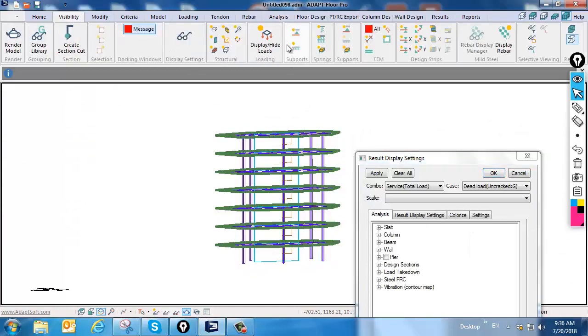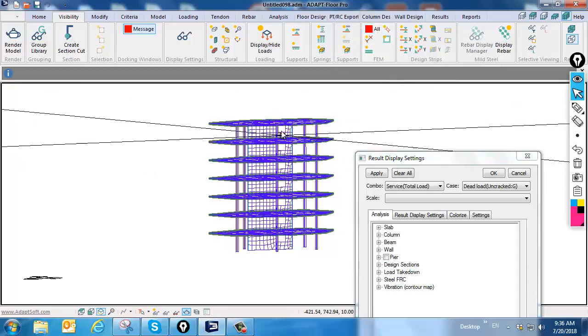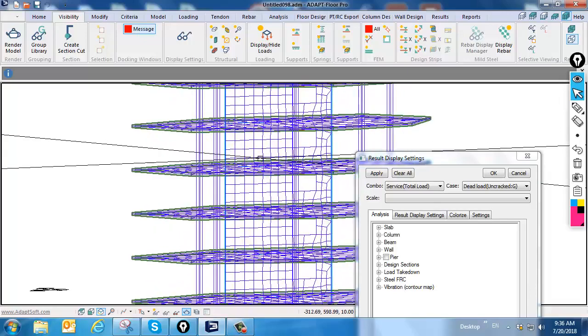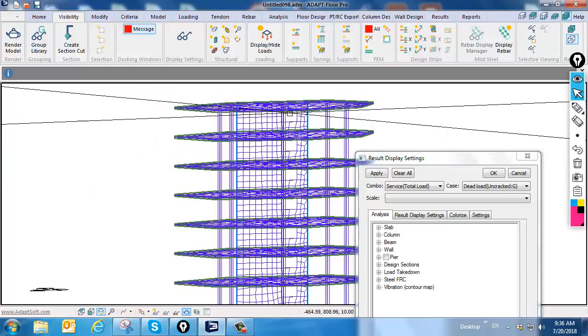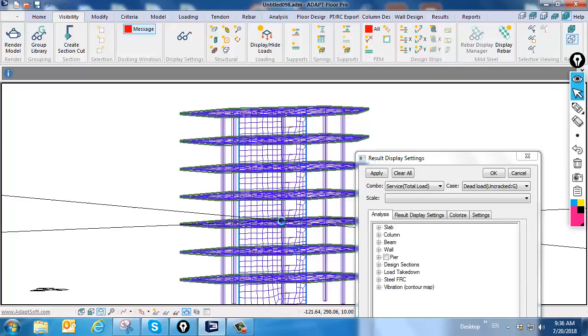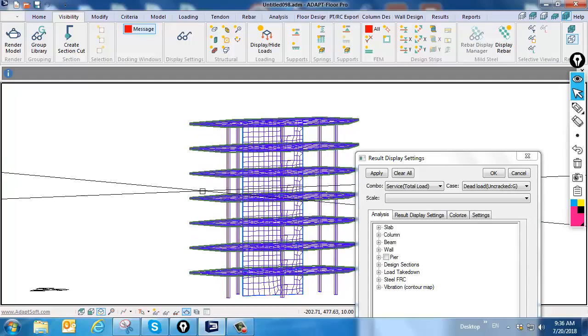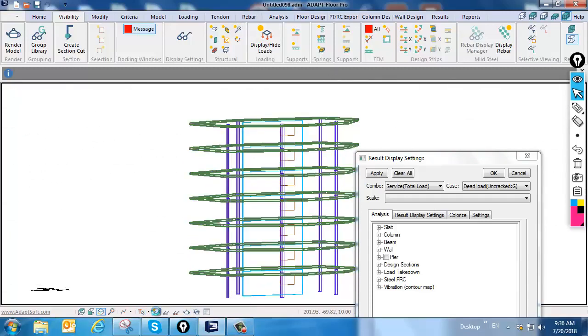I'll go back to visibility to view the wall meshing. And now you can see the wall meshing is much tighter because now it's using, again, a similar approach to slabs. We're using a sparse meshing algorithm, and we have the consideration of wall openings taken into account. If you have a situation where you might want to disregard one particular opening but consider other openings while still taking advantage of the new options, what the user can do, let me go ahead and set the default